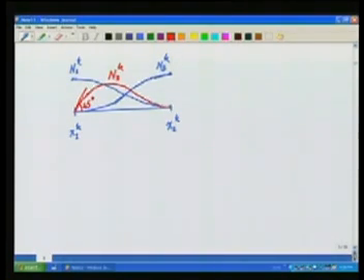Similarly, let me make N4 of k. N4 of k corresponds to theta 2k, right? So it will have a value 0 here, slope of 1 at the point x2, and value 0 and slope 0 at the point x1. So that function is going to look like this. So this is my N4 of k. So these are our 4 shape functions at the element level.